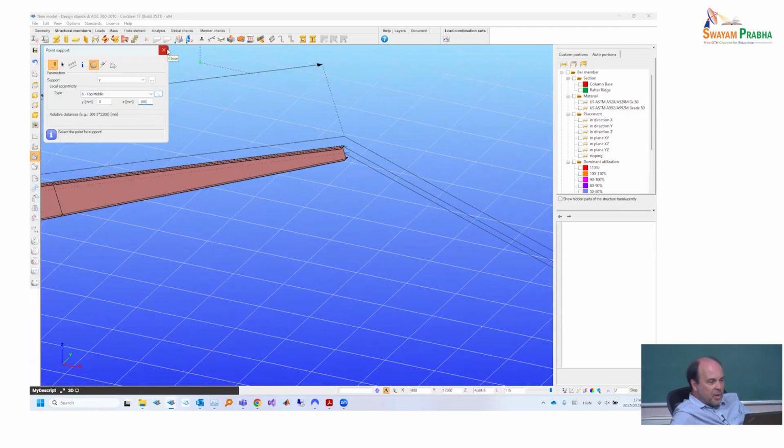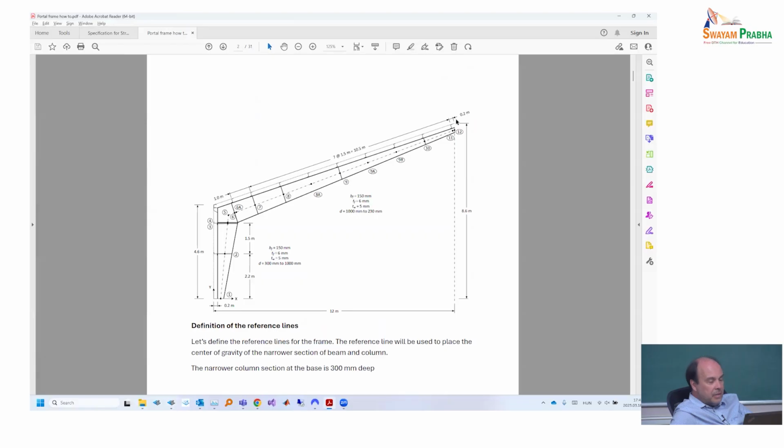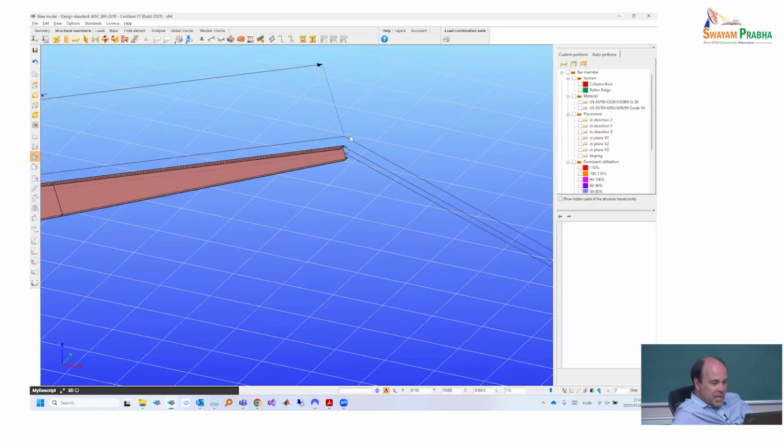Now let's be fully perfect. I delete it, because the distance of the first purlin was defined along the slope, which is funny, and that 200 millimeter on the top is not 200 millimeter at the third line level. So now, because we started earlier from what I made in the PDF, we have the external line, so we can do it precisely. So let's first make a line.